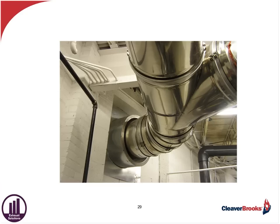Now here's another example of a Y connection, but in this particular case I've got a condensing boiler. I'm coming from the boiler into my common breeching, but I do it with a Y, so I sweep into it, I don't impede flow, and then go into an insulated chase between the walls and up through the roof and outside.